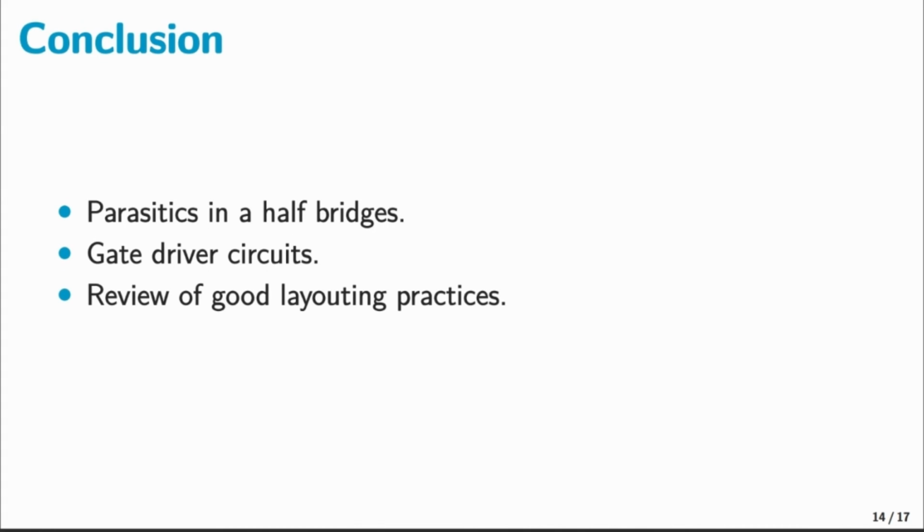To summarize, in this tutorial, we explored the causes and mitigation of parasitic effects in a half bridge, studied a typical gate driver circuit and its key design parameters, and reviewed best practices for PCB layout in power converters.